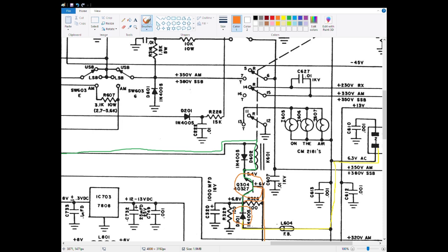The problem I was having was that I had all kinds of erratic voltages at pin 2. And it would be 1, 2, 3, 4, 5, 6, and then all of a sudden it was 0. So I checked and I had no voltage right there at the cathode of D301. But I had voltage to the anode. I had 0 volts at the cathode, so it wasn't a short because I had 150 ohms, so you'd think I have to show some kind of voltage drop there.